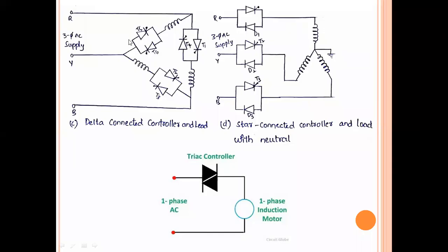See, every power electronic converter generally suffers from a power factor issue at the input terminals. You know what power factor is. Always the input terminals must maintain unity power factor. But power electronic converters are non-linear converters, so due to them the input power factor will definitely be affected.